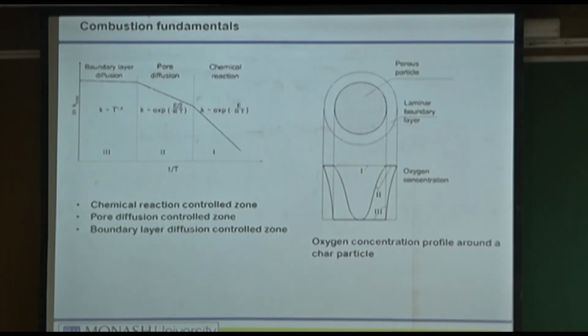So if you have a lot of minerals in it, that means high ash coal, then the active surface area will be a lot less proportionately. Because what's the active surface area? It is the surface area available to the oxygen on the carbon surface. The minerals are not going to react with the oxygen, but the minerals are impeding the access of the oxygen to the carbon, right? So yes, absolutely, mineral matter has a consequential effect. The structure also has a consequential effect on it.